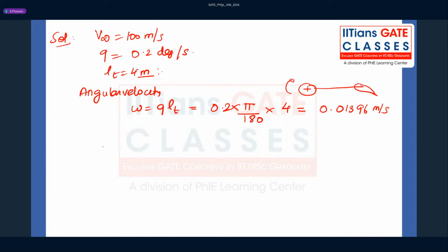So which means what will be my, I know from the equation that it's not angular velocity, it's tangential velocity. Mind you. I know from thin airfoil theory that, let's say I have a free stream wind coming in like this. Let's say V infinity. Let's say this is the downwash coming in. So which means this is my angle of attack. This is the downwash angle, which in this case is my angle of attack. So I can write simply tan alpha as W by V infinity.